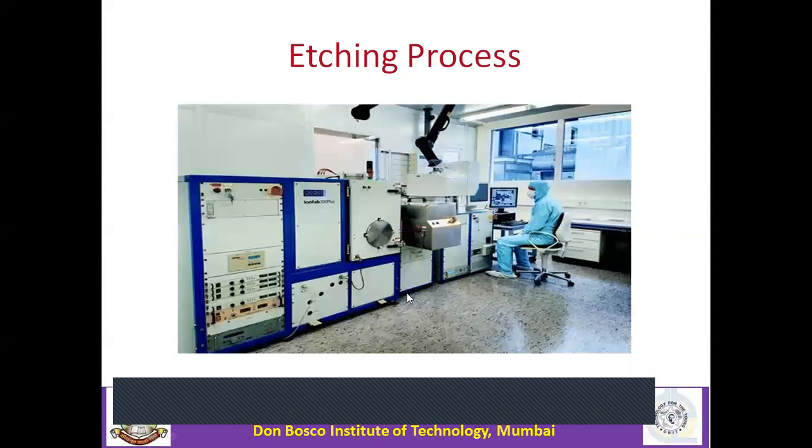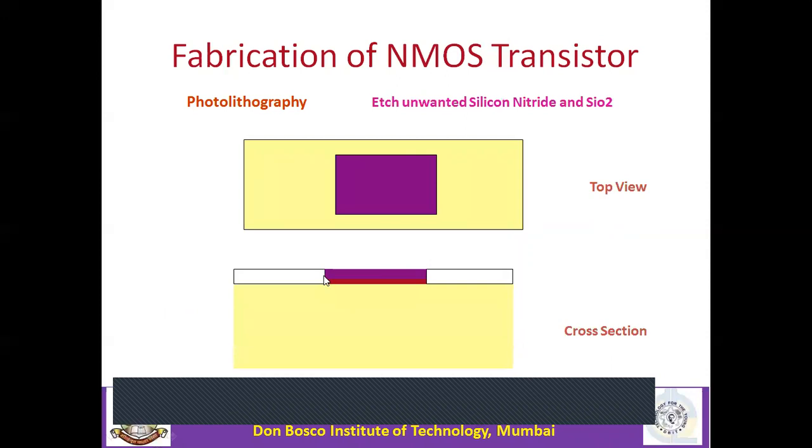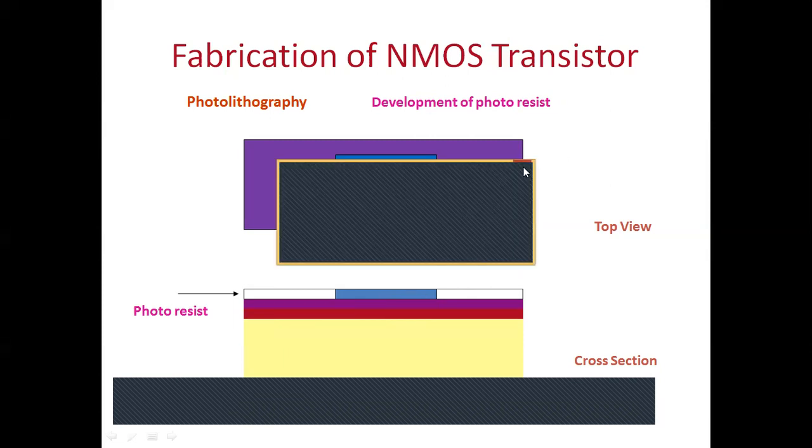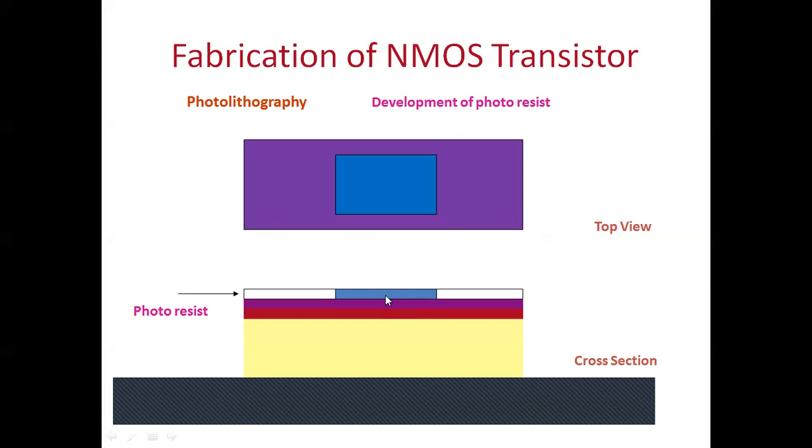Now next is the etching process. Etching means this whole structure is kept in etchant, and this engineer is observing what is happening during the etching process. See here, it is etched away. Whatever was exposed, this much portion, is etched away in a chemical solution. But nothing will happen to the portion just below, the hard photosensitive material.